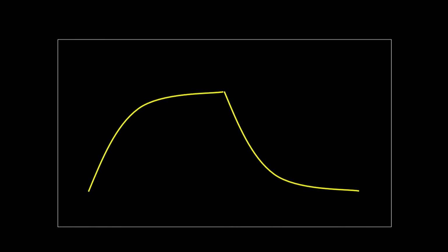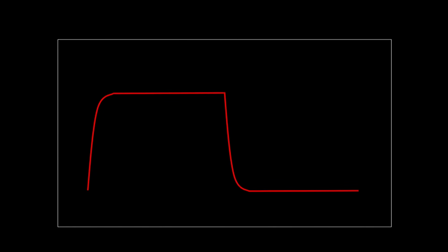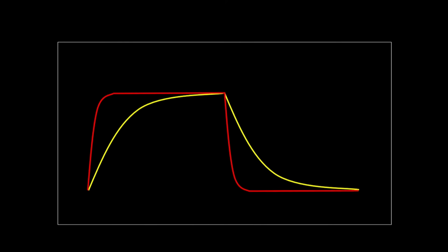A larger capacitor will have a slower circuit. So you will notice that when you connect a smaller capacitor, you'll get a steeper curve, like the one shown. Here is a comparison between the two. Notice that when you have a smaller capacitor connected, the time constant is smaller, which means that smaller time is required to reach the maximum voltage.